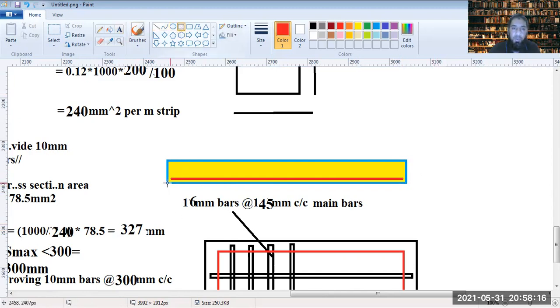There is a support on all the four edges. So there are supports here. What is happening towards the ends is that although this is hogging, sagging moments are being generated here in this case, there is a certain amount of negative moment acting at the end here, somewhere here. Certain amount of negative moments acting here and here.